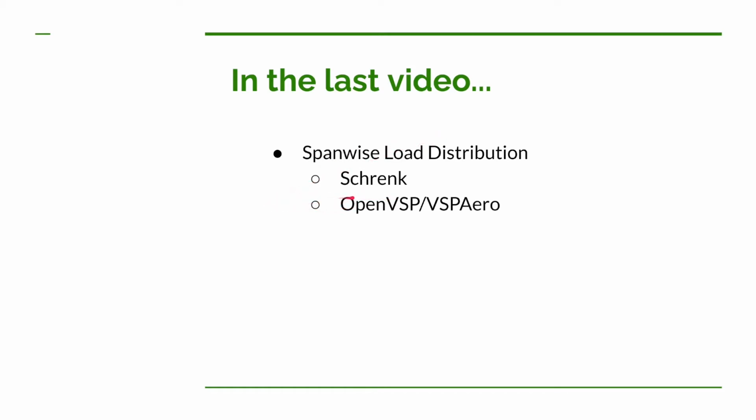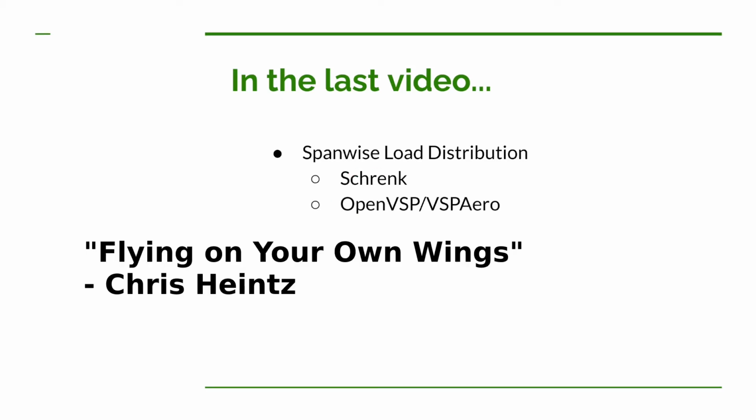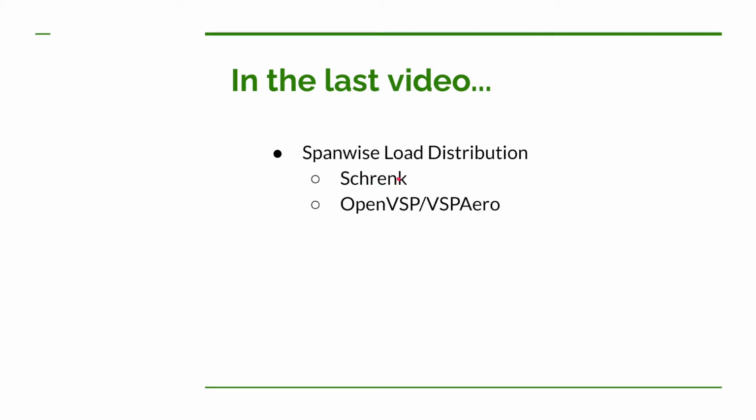But in that previous video, we used two ways to come up with it. One was with an estimation method that Chris Heintz used in his book, Flying on Your Own Wings. Now, it's very conservative. In other words, it overestimates the load out on the wingtips, which puts more bending moment on your spar. And then we used OpenVSP with its aerodynamic analysis, VSP Aero. Well, in this video, we're going to continue using VSP Aero.